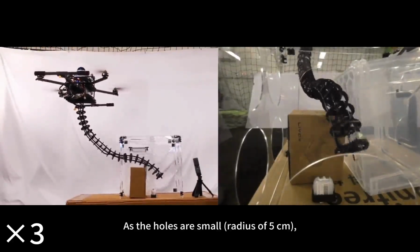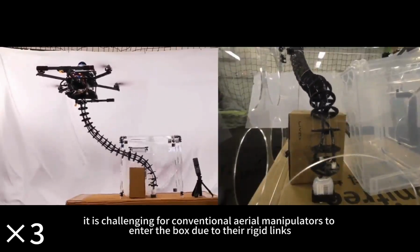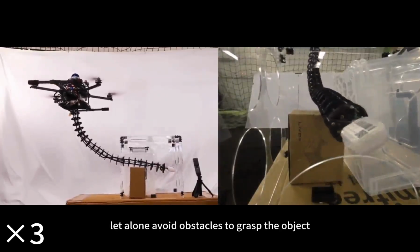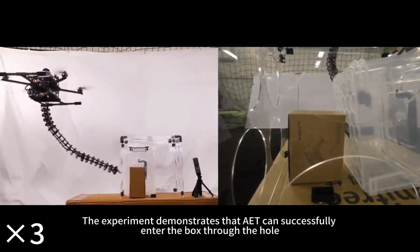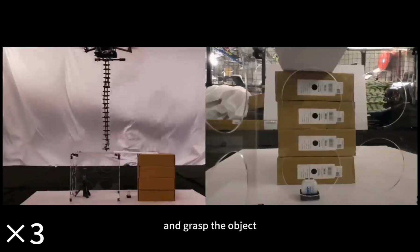Then, we put the object in a semi-closed box with circular holes. As the holes are small, with a radius of 5 centimeters, it is challenging for conventional aerial manipulators to enter the box due to their rigid links, let alone avoid obstacles to grasp the object. The experiment demonstrates that AET can successfully enter the box through the hole, avoid the obstacle, and grasp the object.